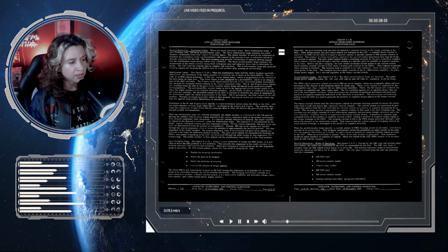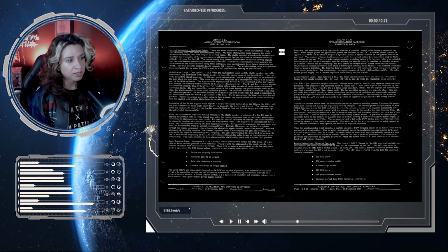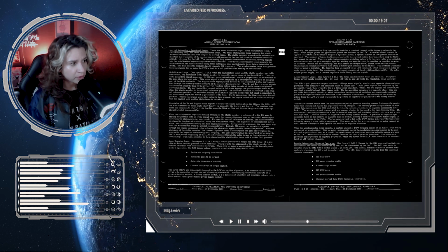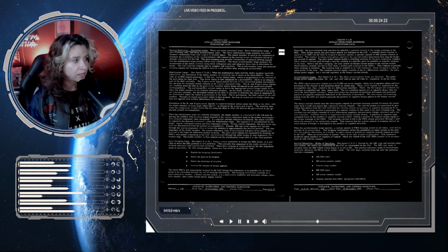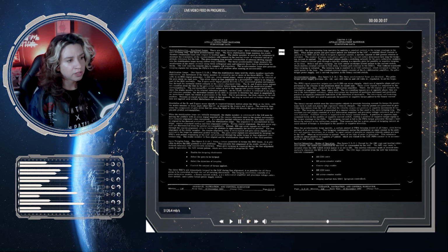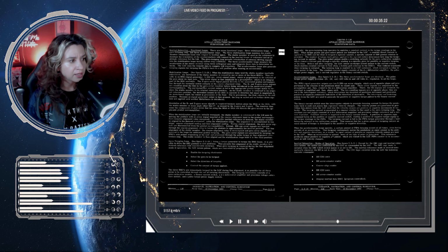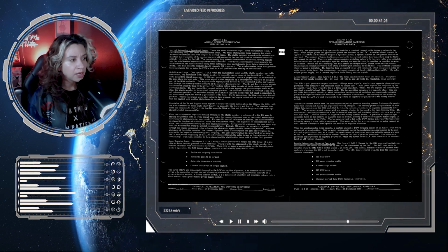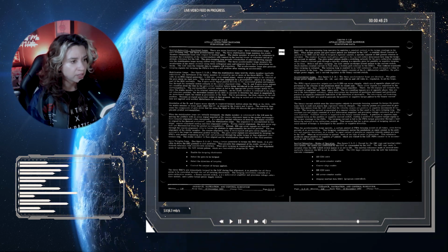Instead, 800 CPS error signals are injected through the coarse alignment relay to torque the gimbals to approximately the desired position. For fine alignment of the stable member, the coarse alignment relay is de-energized and gyro error signals are injected in the loops for additional gimbal torquing. The gyro error signals are generated by torquing the IRIGs with pulses originating at the LGC and processed through the pulse torque or fine alignment electronics loop. The stable member is then aligned, and the stabilization loops hold it in its final position.